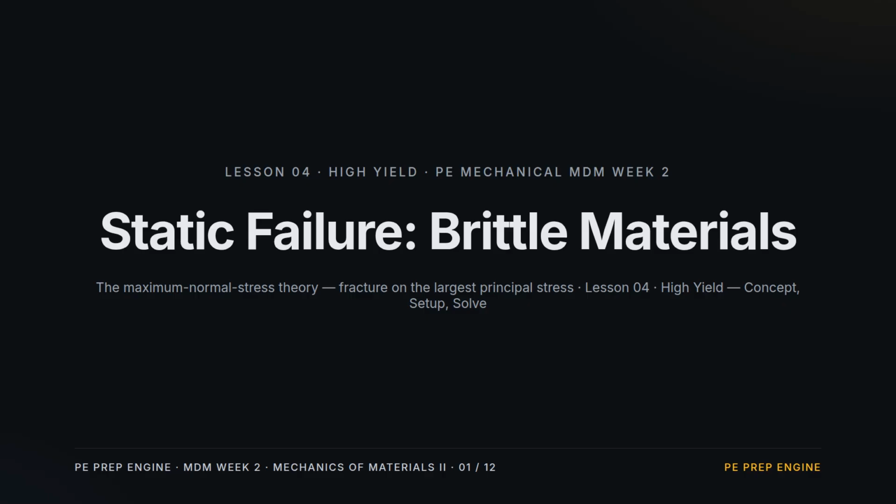3 ideas run the lesson. Brittle materials fail on the maximum principal stress. They have different strengths in tension and compression, so you run 2 separate checks. And the principal stresses come straight from Mohr's circle, including the out-of-plane zero you must not forget.